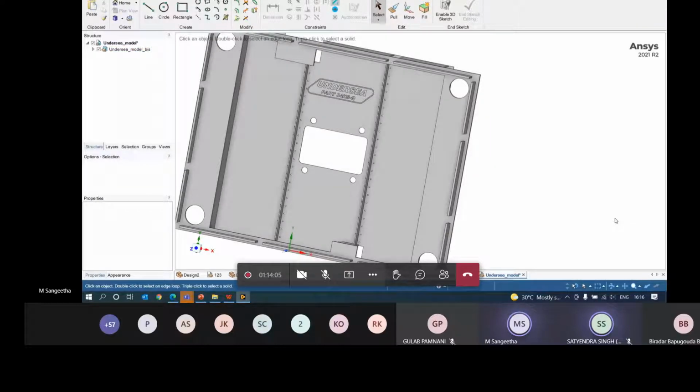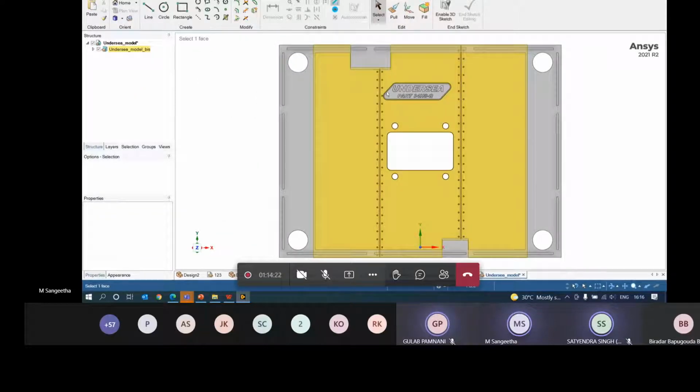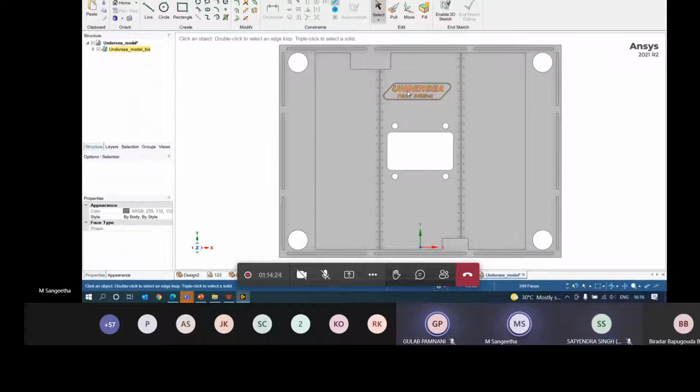If these imprints exist, it will create some problem for me in terms of surface body creation, because we spoke of having a uniform cross section throughout. So for that reason, first we'll set our view and select only the imprint, or you can select the complete flat surface where the imprint is done and say delete. So that is gone, right?